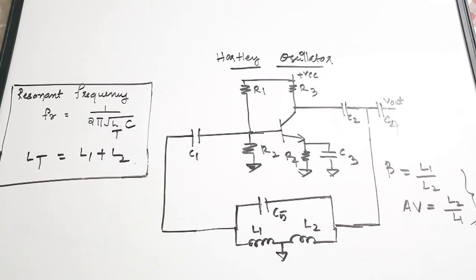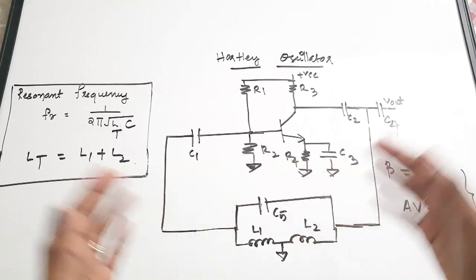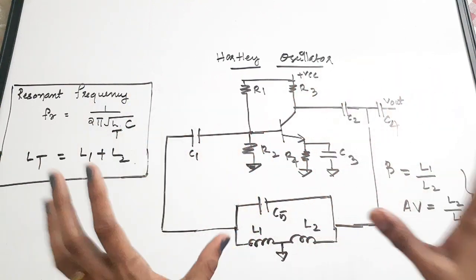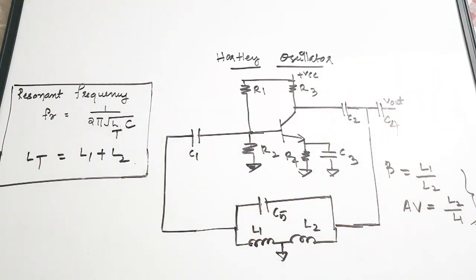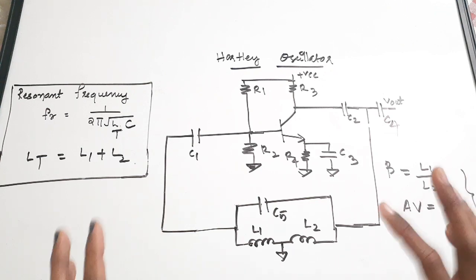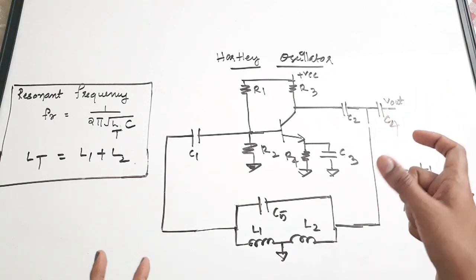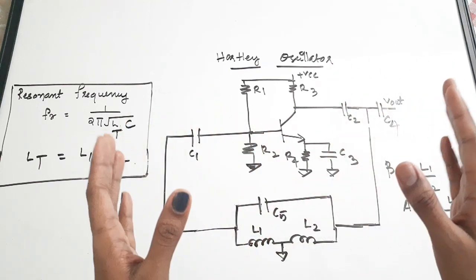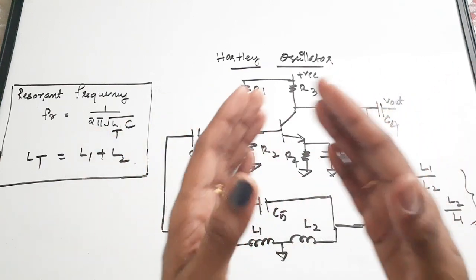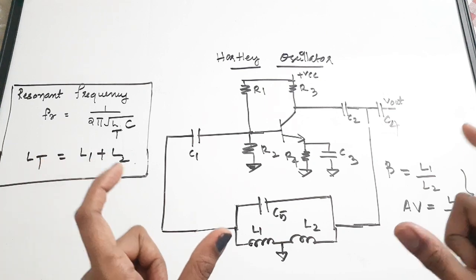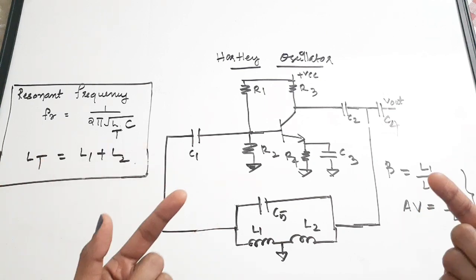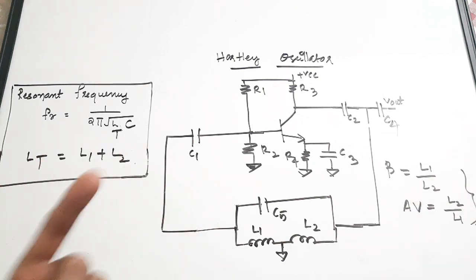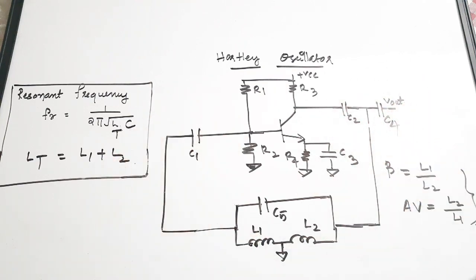In these three oscillators, the amplifier stage is almost the same, or exactly the same, you can say. Now in some figures you can see these coupling capacitors, in some figures you cannot. This generally represents an amplifier stage. Just know that this is an amplifier stage and we are using a common emitter configuration, which you have to use if you are using a BJT.